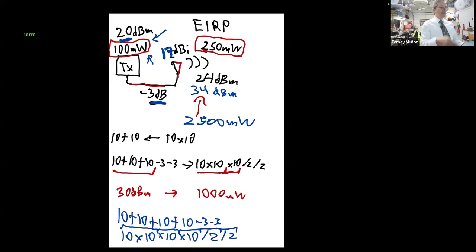How much lower? Well, low enough that it's going to stay within the 30 dBm requirement. Okay? So it's going to be what? If I added 10 in here, you just remove 10 in here, so you can only go 10 dBm on this side. So just 10 milliwatts.